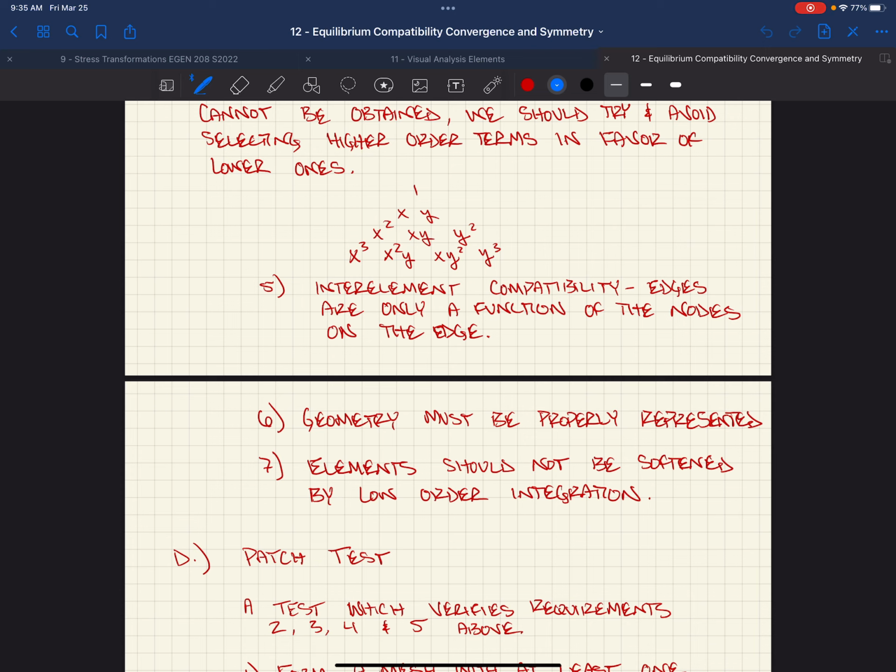Yes, Max? So in ANSYS, we picked whether we were going to use a plane 42 or whatever type of element, but in VA and other programs, they just pick. In structural engineering programs, they have elements that are pre-selected. So you say, I want to model a beam, and they have a beam element, and that's the one element they use. They make sure that it does all this stuff. Well, that element has been selected in such a way that we try and use a complete polynomial.